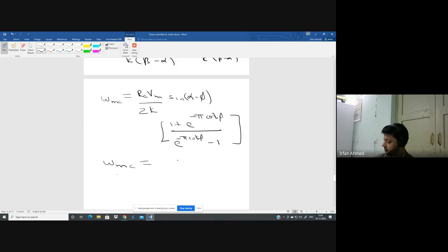Okay. So suppose the critical speed is, let us say, 1000 RPM. I'm converting it into RPM instead of radian per second. Suppose the critical speed is 1000 RPM and the actual speed is 1150 RPM. So tell me whether you will get continuous or discontinuous conduction. Is everyone clear what is critical speed?